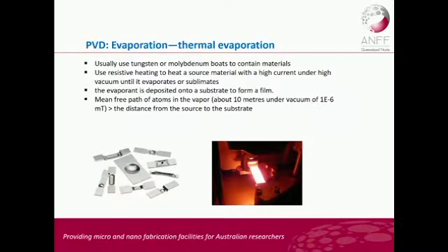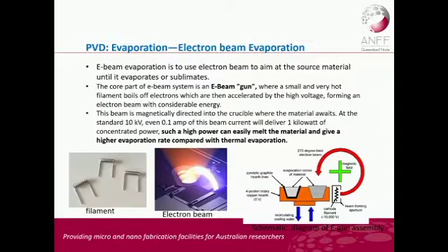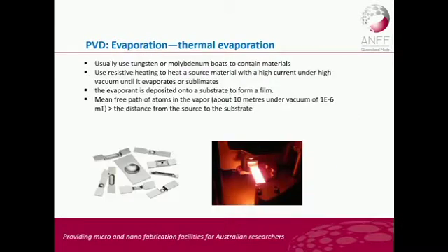So what is thermal evaporation? The first one is where we use resistive heating to heat the source until it vaporizes or sublimates. Then after that, the evaporant will deposit onto your substrate because of condensation.